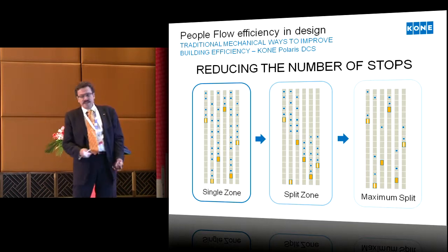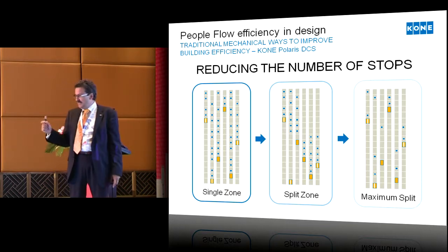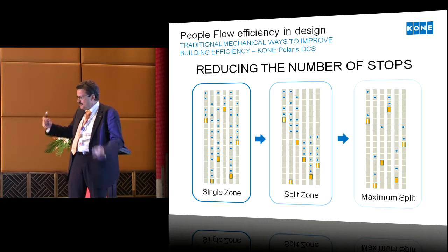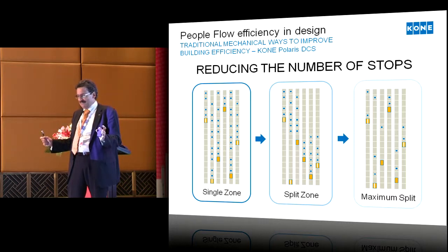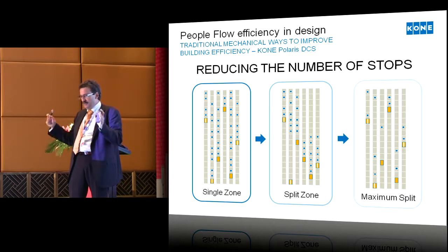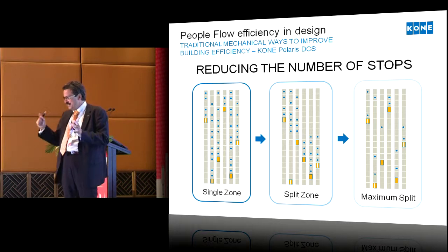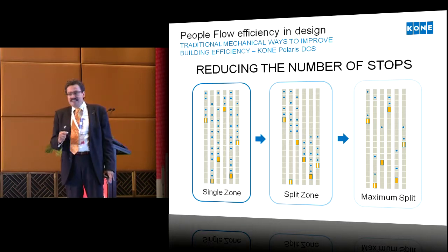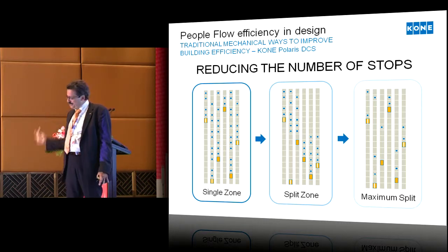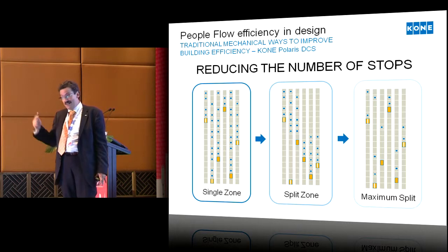So we're now actually in a system where every car has its own zone. If you have a conventional destination system where you have all the DOPs on all floors, the destination operating panels where you enter your destination, then you can't enter the other car arriving. You have to enter the assigned car. So that car is your zone, and you can't use the other zones.